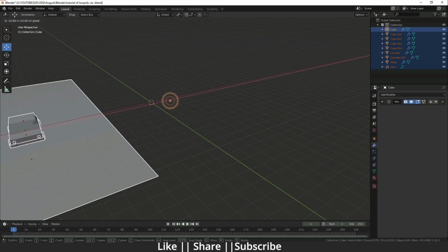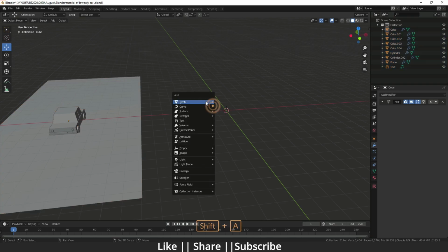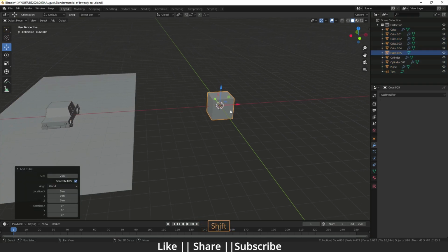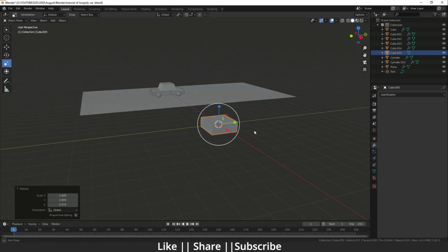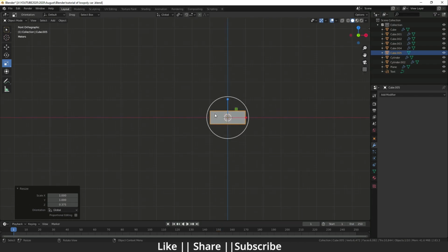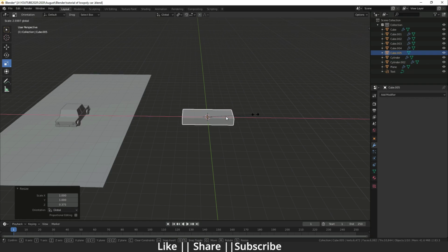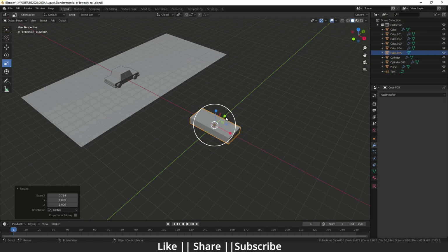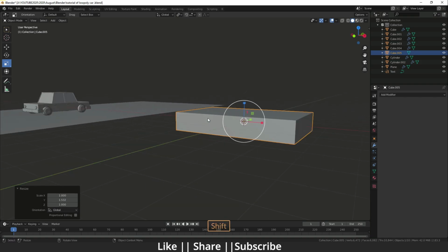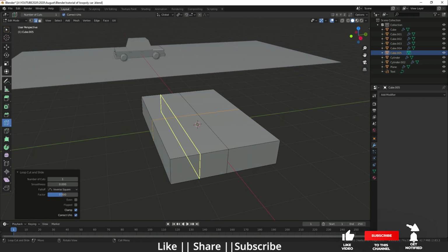I'm just going to keep it beside this, and I'm going to add one cube here. For that I will press Shift A and add one cube, and after that I'm going to scale it down like that. I think that is enough. Yeah, okay, and I'm going to scale it like that. Yeah, that is enough, and a little bit like that. Then after that I'm going to add one edge loop here like that, and one edge loop here.